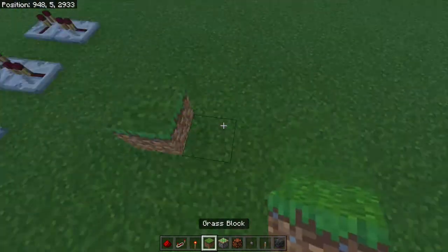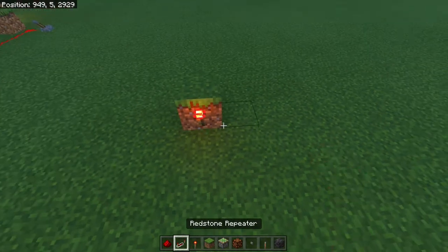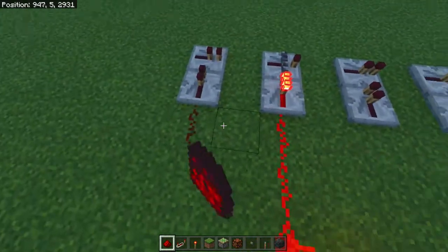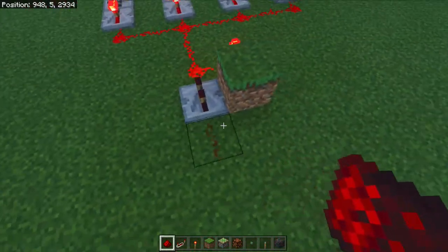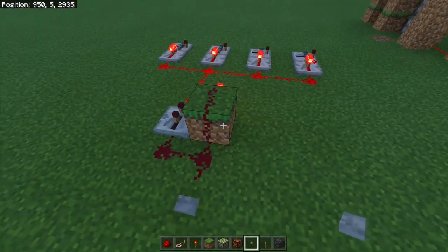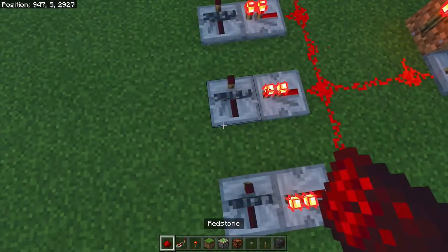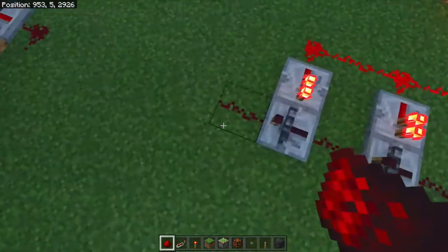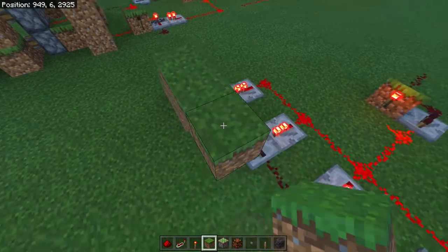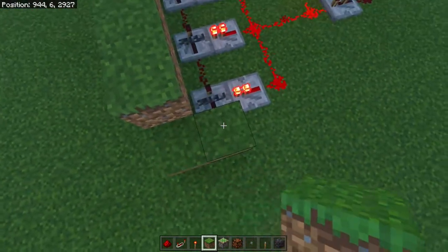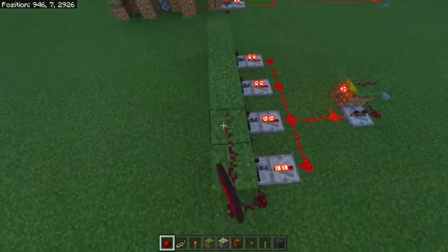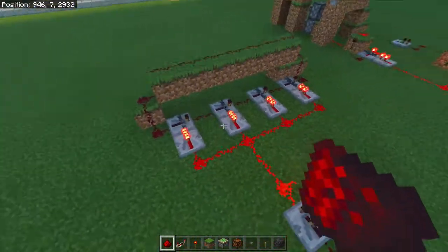And I'm going to set up that rising edge filter again over here. So don't forget to put the 1 tick delay on that. Alright, and then have our input. We'll have a button here. So, and then of course we'll do this and we'll put them in a loop here. Let's have those 4 in a loop.